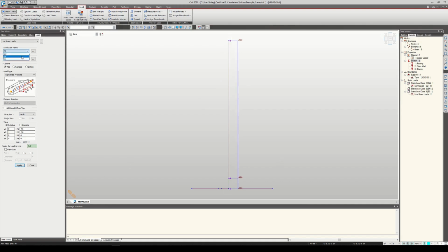Next, let's do our EH. Again, local Z, but instead it's 0 and 672. You see it went the wrong direction, so you can just click undo and just switch these. Depends on the order of your nodes, but you can just do it like I'm doing right now. Just switch P1 and P2. There we go. It even calculates what the pressure is here at the top.